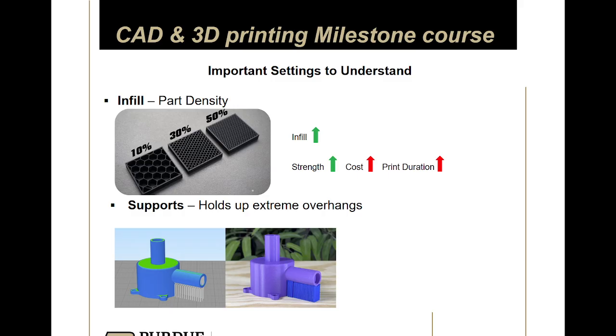All right. So underneath that is support material. 3D printers are not a perfect process and they can't make absolutely anything. You'll probably encounter times where you'll have some kind of overhanging area and a 3D printer can't really print in midair, right? When the material comes out of the nozzle, it's molten plastic, so it'll droop and then it'll flop over.